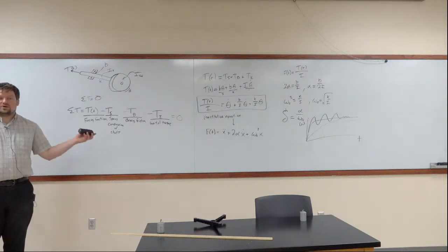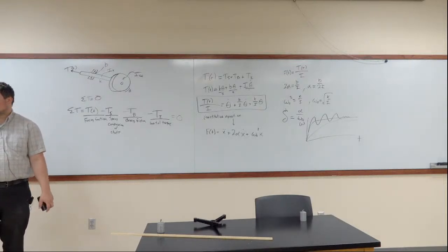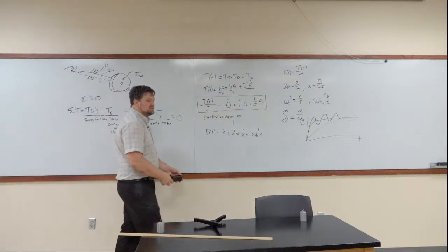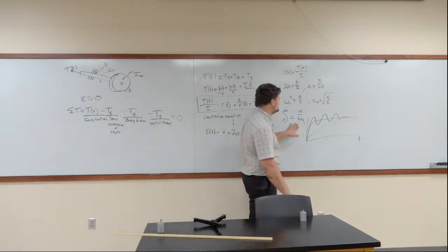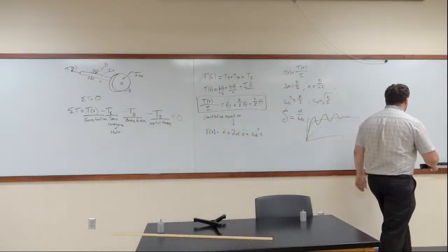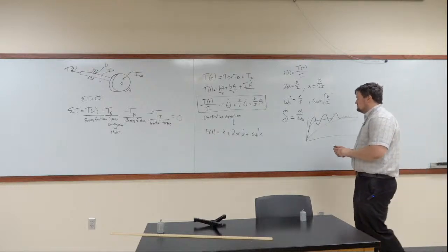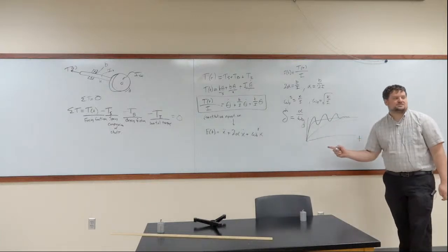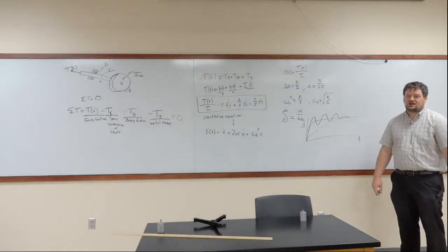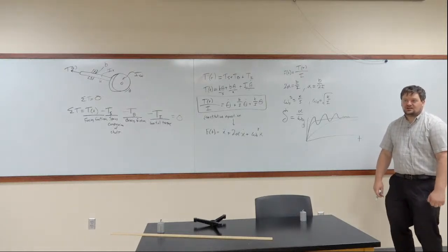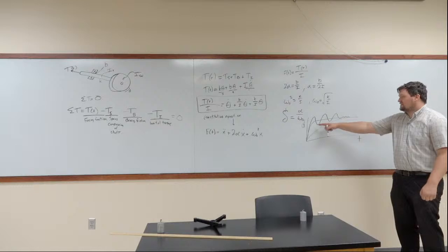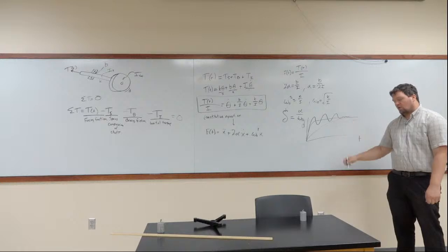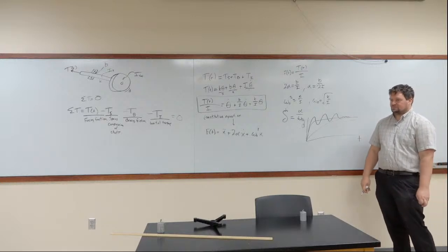Well, this is also true for linear translation systems. In a very simple model of a vehicle suspension, you have these three different types of suspension. Now we're going to put this as displacement quickly. How many of you have ever ridden in an old truck? You hit a bump and you bounce for a bit? That's doing this. It's the oscillation. In that case, the suspension is an underdamped system.